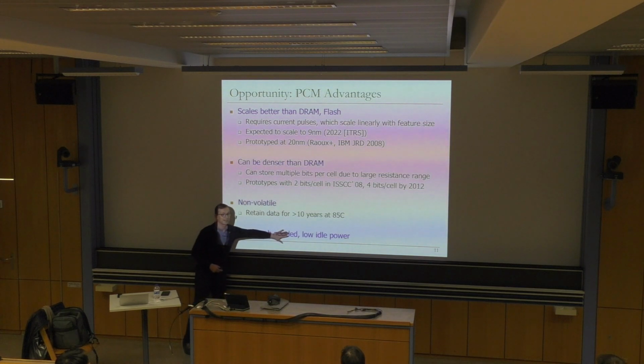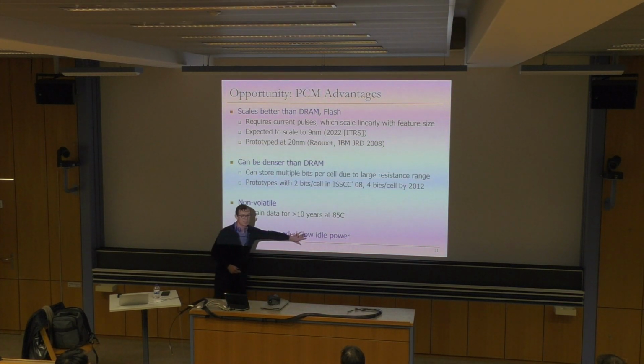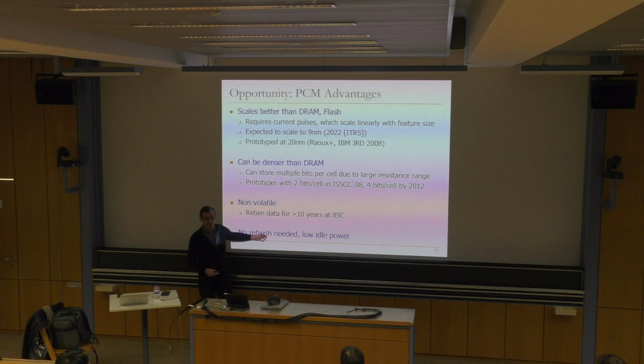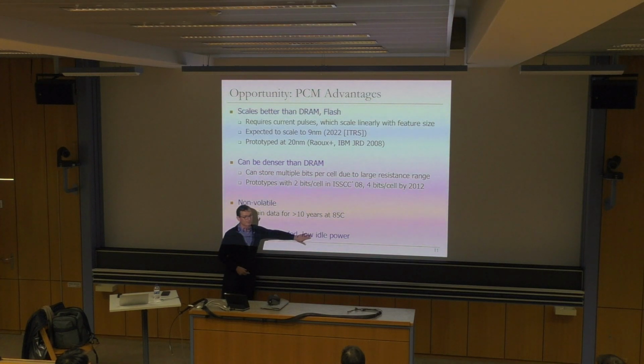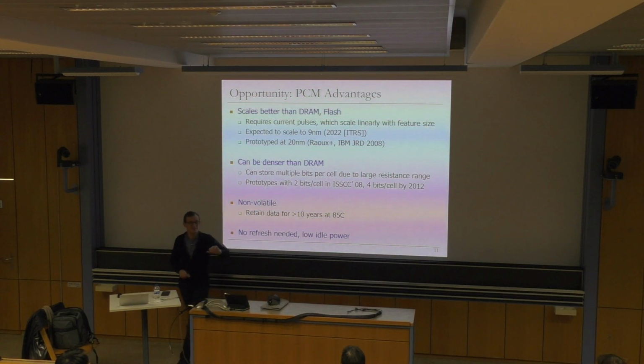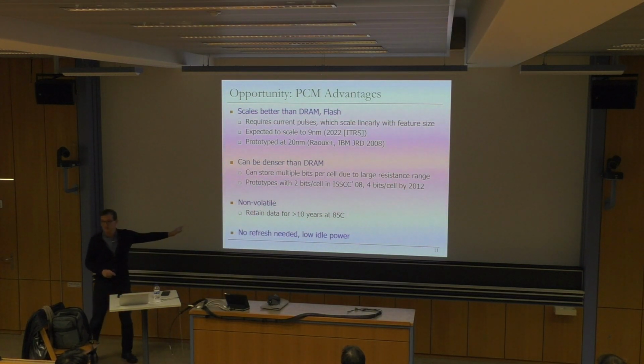So you gain a lot of power reduction because you get rid of refresh, and you remember refresh was really the scaling limit of DRAM, and we kind of got rid of it at this point. And the static power is also gone for practical purposes, let's say. Clearly it's not gone, there's always static power, but compared to DRAM it's gone. So there's going to be a big energy advantage of these technologies also.